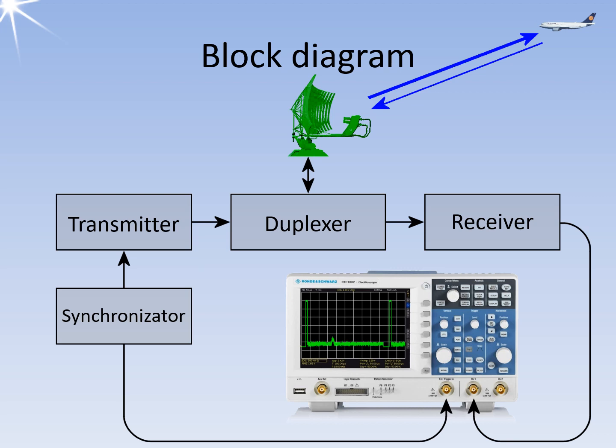Representative of a large number of radar scopes, a simple oscilloscope is shown here as an analog A-scope. This screen is also only a computer-generated image. The A-scope shows a video amplitude as a function of time. The linear x deflection is proportional to the propagation speed of the electromagnetic waves in space. Thus, the runtime is proportional to the distance from the reflector.